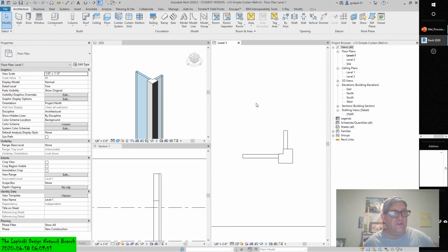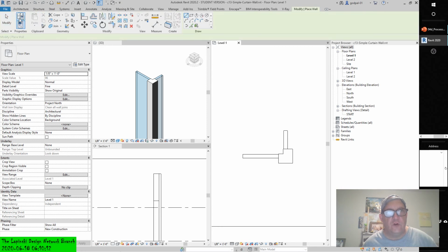If you have already placed a regular mullion at the end of a curtain wall segment, select the mullion along the vertical edge and then use the type selector to choose a corner mullion type. Remember that you can use the context menu, right-click and select mullions on the grid line to make the selection easy. So, again, just to go through the process, you'll also draw a curtain wall.